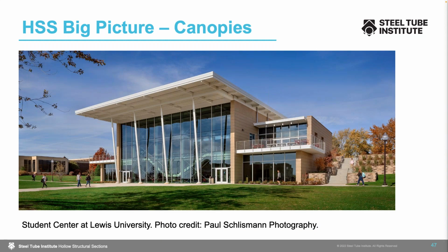There is some guidance out there to provide a minimum diameter of 1/2 inch for that weep hole. And if that member is exposed and galvanized, then that weep hole can also do some double duty for you, serving as a vent hole in the galvanizing process as well.